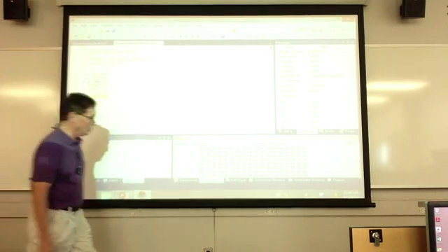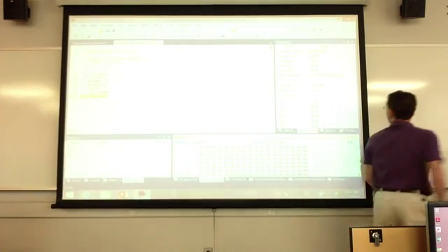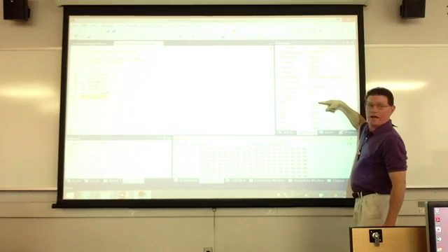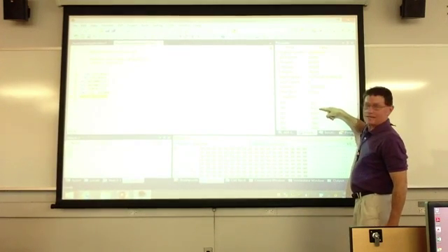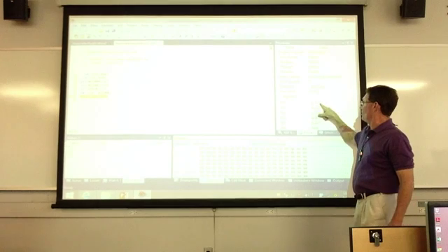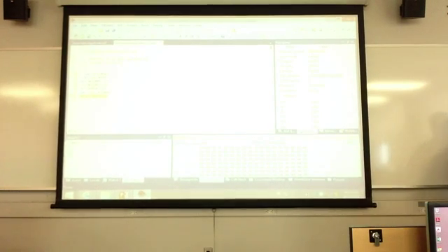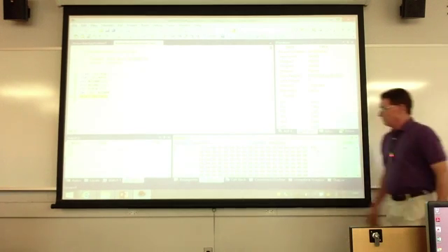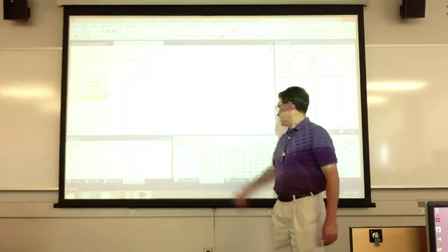And you will see, if you notice, R0 has the A3 in it, R1 has the B6 in it, because that's sitting at memory location 0 and the other one's sitting at memory location 1. So I go in here and I simply go down to where my general purpose registers are at 0 here. I see the A3 and that is sitting there.